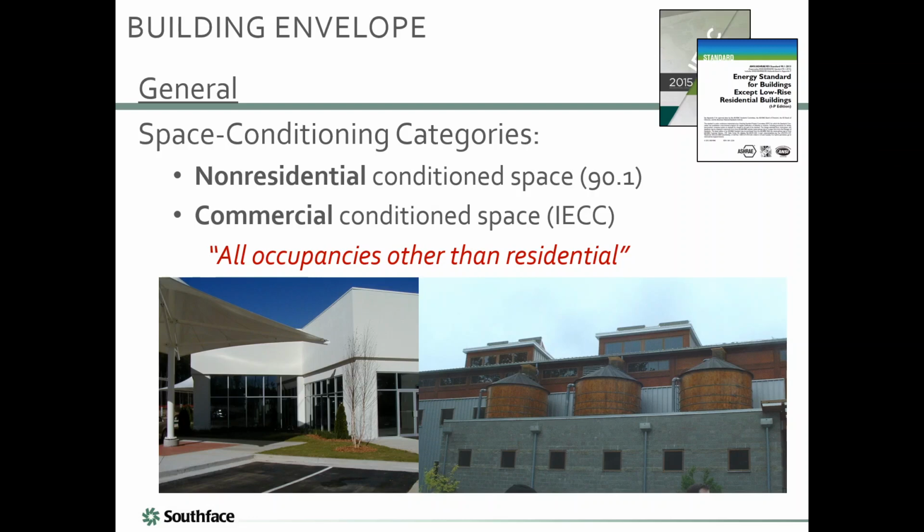And only ASHRAE has this option, which says we can potentially put just enough heat to keep the pipes from freezing, but it is not much. And in my climate zone 3, 10 BTU per hour per square foot is not very much. If you have a 5,000 square foot warehouse, you would be allowed to have 50,000 BTUs of input of gas heat. That's one very tiny hanging gas space heater. And I guarantee the designer is going to say, oh no, I'm going to hang 8 of those.